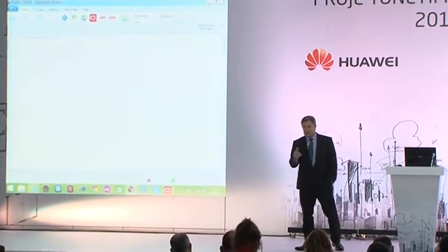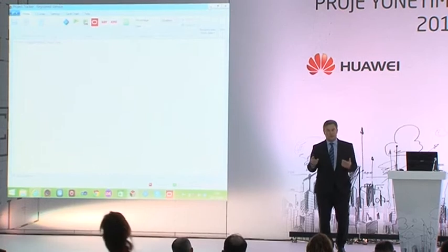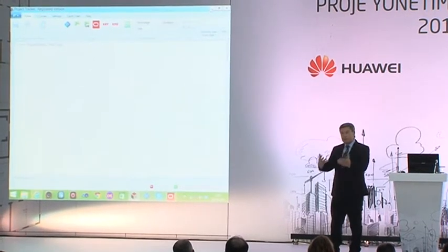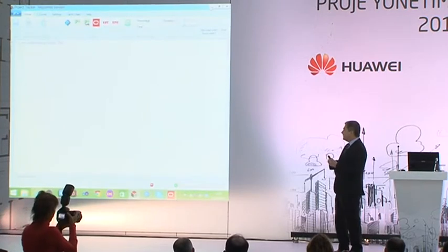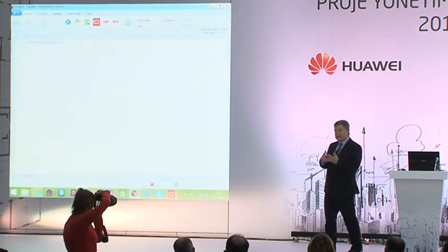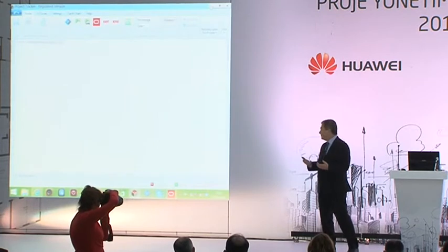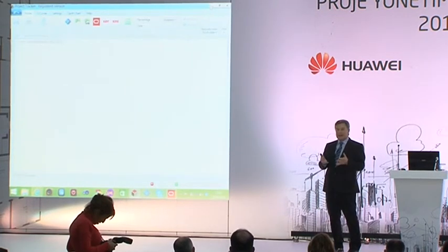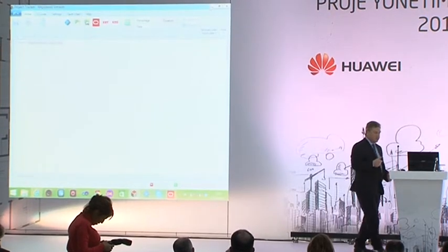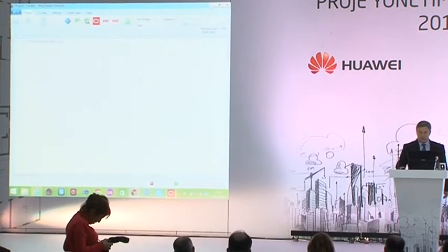And because we're importing the XER file rather than export to Excel, I'm importing all of the data. So as well as being able to create an S-curve, we can also look at Gantt chart data. We can look at plan versus actual progress. So there's a little bit more in it than importing just the S-curve. So we're going to do the XER format now.